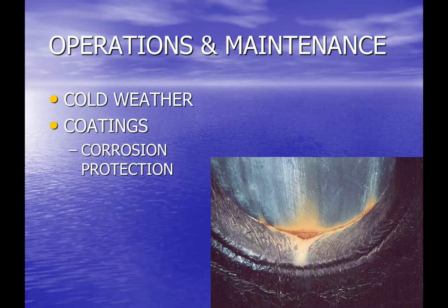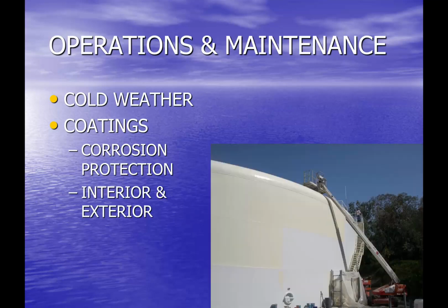on steel tanks, and as we've talked before, steel tanks can corrode just like a steel pipe would. It gets worse as the water's a little bit warmer. pH can impact it. The presence of total dissolved solids can increase corrosion. So a variety of just normal water quality issues within a reservoir can exacerbate some of those corrosion issues. So coatings is one of the ways, especially on steel tanks, both on the interior and the exterior, that will help to protect the steel structure of the reservoir.